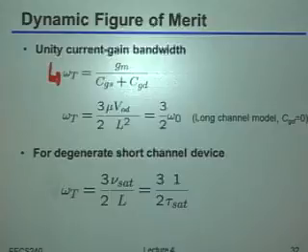I did want to mention a couple of brief things, though. Taking our long channel transistor model as a simple example, you could pretty much directly calculate omega t based on the definitions of gm and what the total CGS and CGD would be, as a function of a few fairly simple parameters. Obviously the mobility comes into the picture.